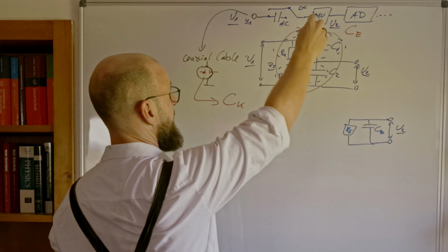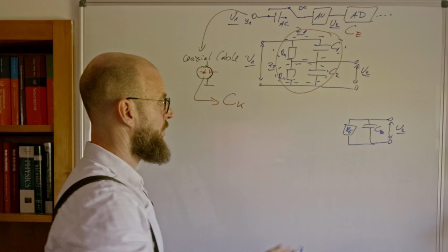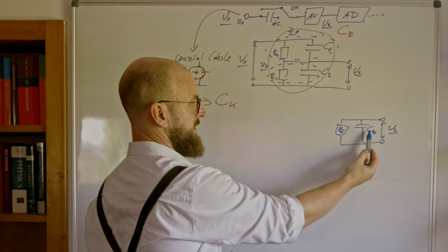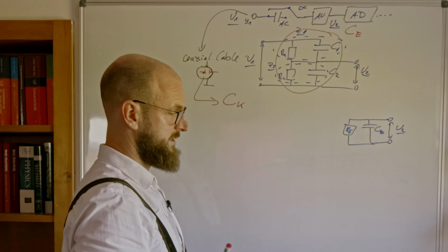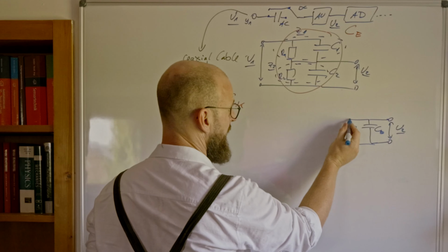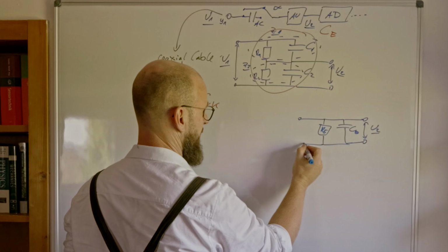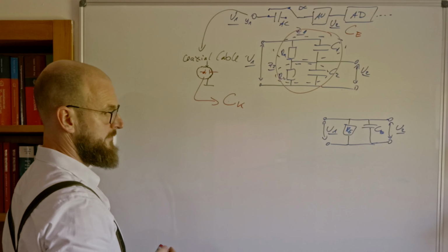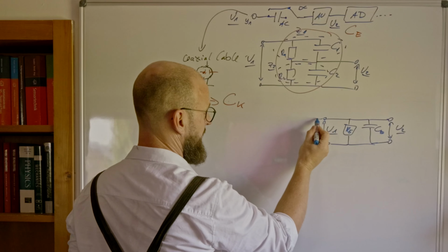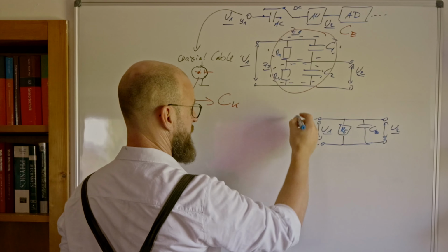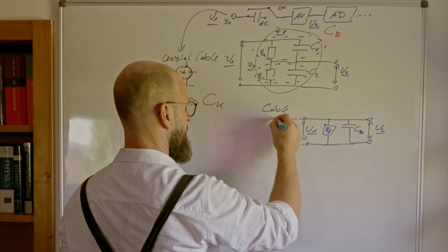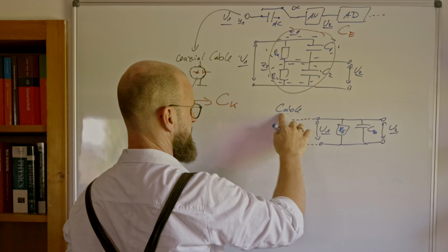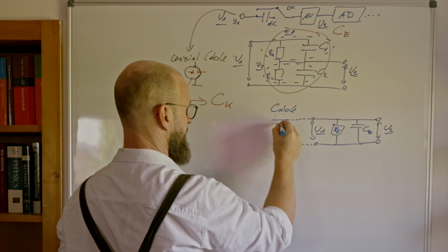Imagine all of that adaption unit and all of the oscilloscope combined into those two parts, the ohmic resistance and the capacitance of our oscilloscope. Now those are connected on the other side to our U1 over here. And now that stuff, we get the cable over here, which holds its own capacitance. Let's paint it like that.